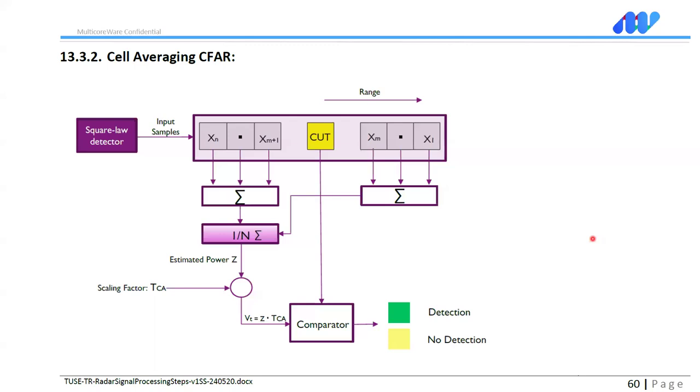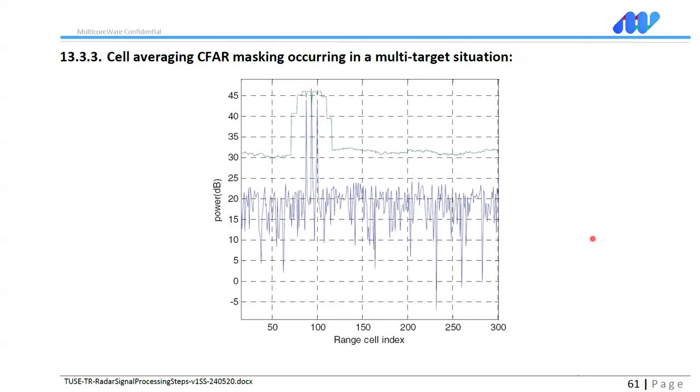They all mean the same, but give different results. And especially for radar, you need to be very careful because in theory, you always assume a normal, Gaussian distribution, but I personally worked on it for at least a year, and it's definitely not Gaussian, especially after beamforming. It's wildly different, and that's an important thing.